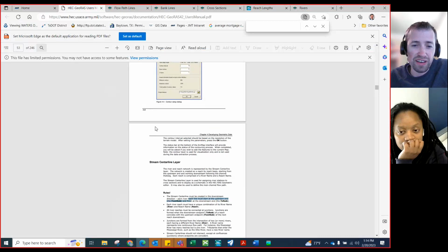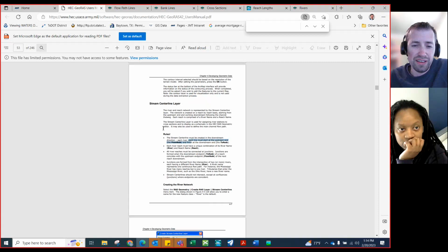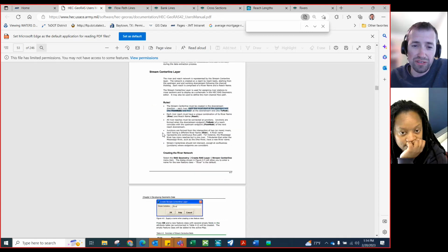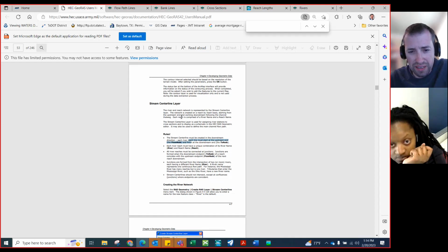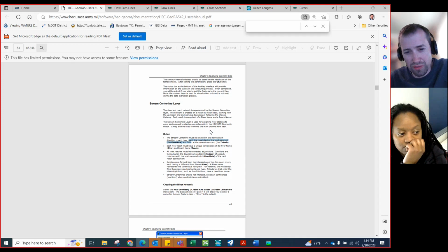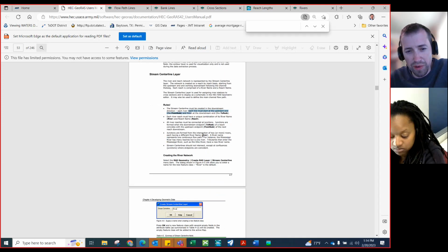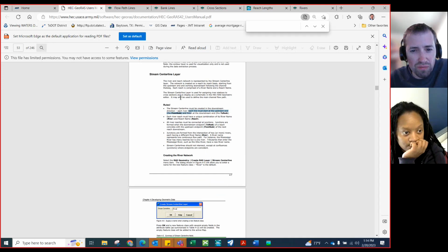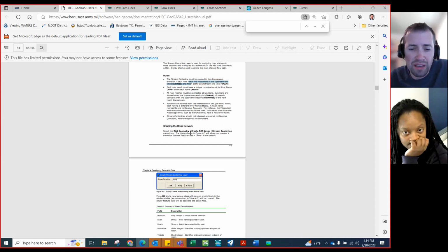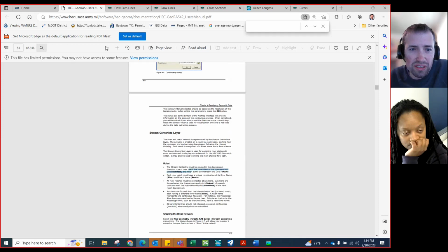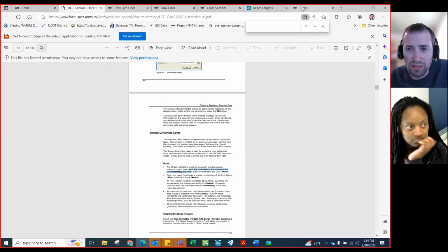The HEC RAS user manual is excellent. I think it describes a lot of the things that you do for creating one. I haven't used HEC RAS in a while, but it's very similar to the way you do it in ORD, and it just gives a lot of helpful descriptions. I think it might tell you to draw the stream the other way from the way you do it in ORD, from upstream to downstream. But in ORD, you draw it from your downstream and then go upstream.